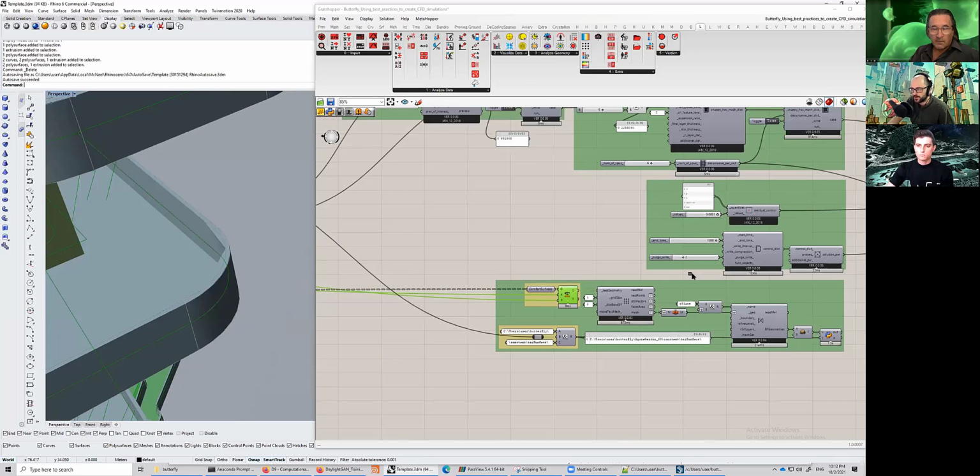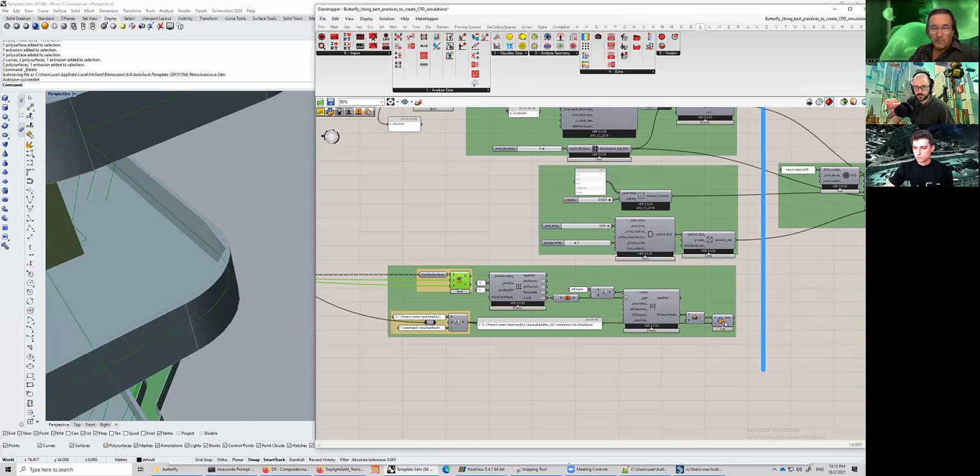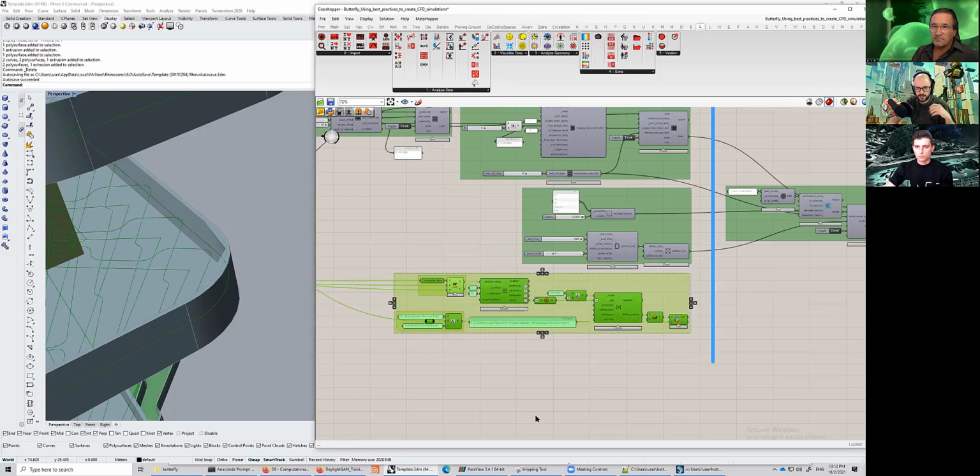And with this small native Grasshopper, Butterfly exports them as STL, and then while you run your case, during runtime, it will save velocity values here. So when you come back, you can simply load these values, even in Rhino, and they will come colored with the wind velocities and everything. And I will share the scripts later. I think this is very powerful. It saves me a ton of time in post-processing.